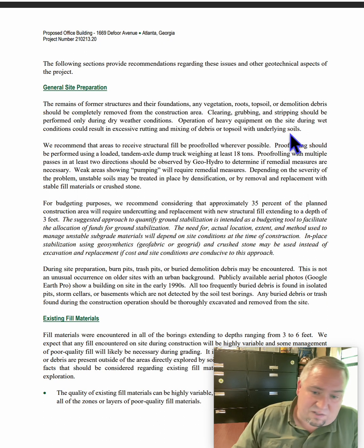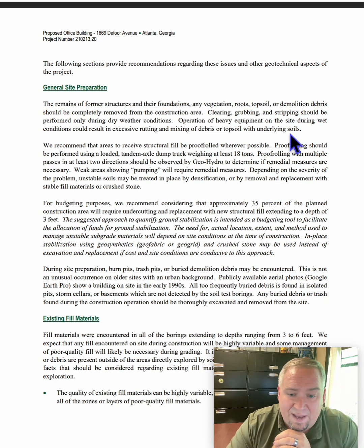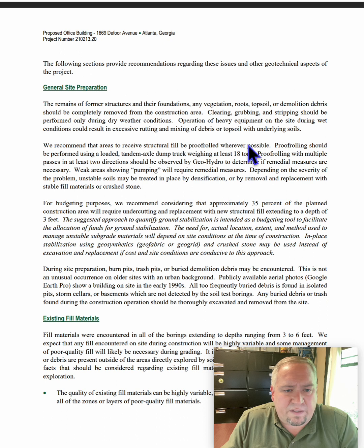So when it's dry, let's strip all that stuff off and consolidate it. The geotech will come out there and qualify it. If it's outside the norm of standard roots and tree debris, the geotech will qualify that. We'll take those to the C&D construction demolition disposal facility, and the regular tree material we'll isolate over here, which should be within our contract ideally, and that'll go to the inert facility, which takes all the organic stuff that can rot. So they're already letting you know, hey, do this thing this way. This is how we want it done.